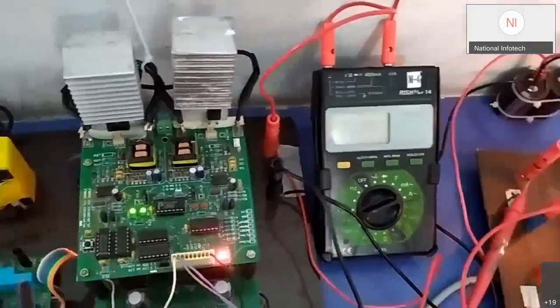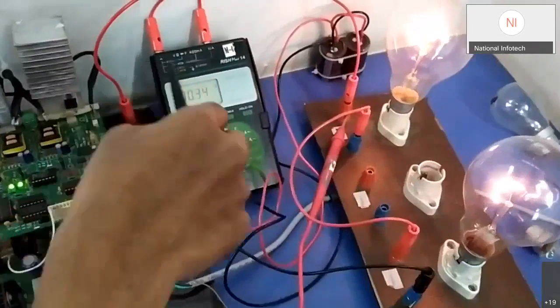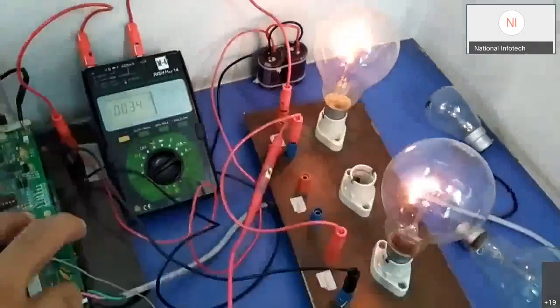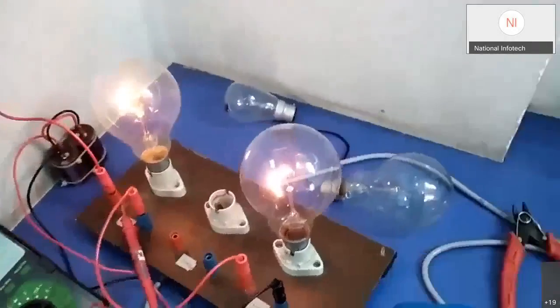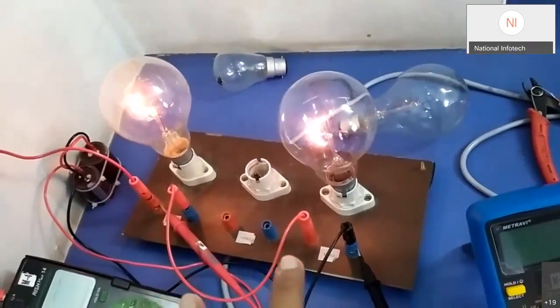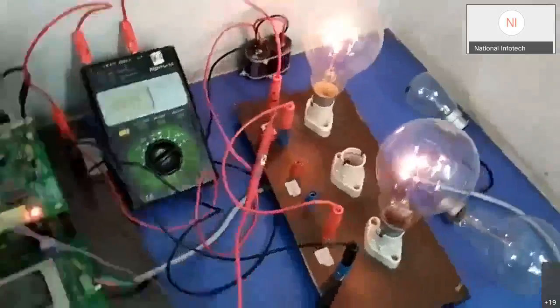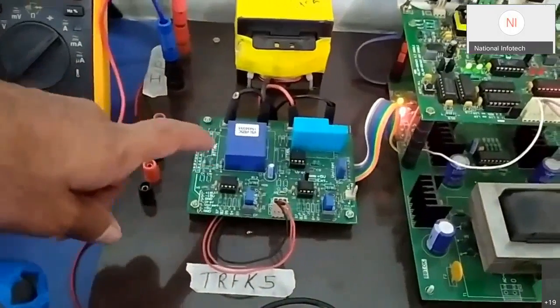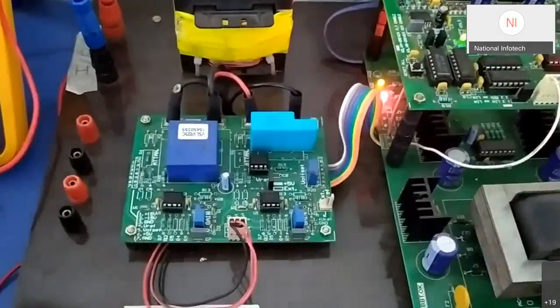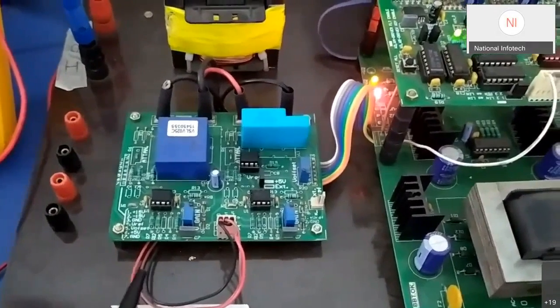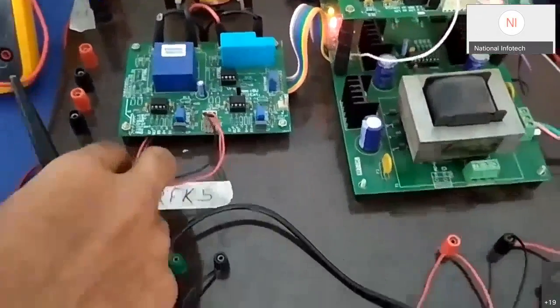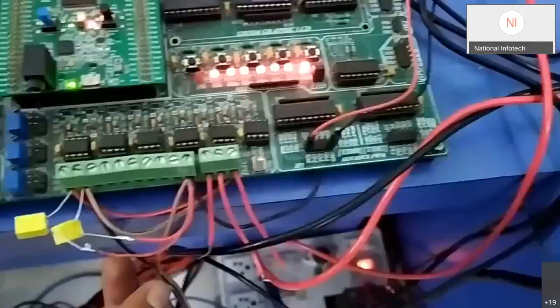Okay. Moving on to the output side. At the output, the capacitor is connected in parallel, and we have connected a 400 watt load, which is these 2 bulbs of 200 watt each. So coming back to the controller, let us first understand the sensing. This input sensor which we have connected at the panel terminals, we are terminating from here to the ADC channel of our